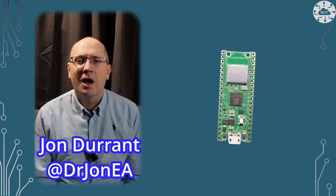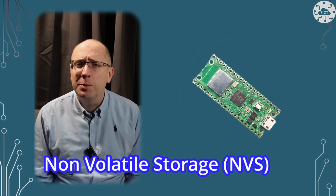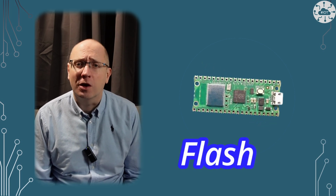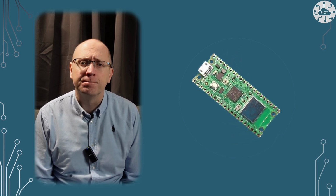Hi, I've been taking another look at non-volatile storage options for the Raspberry Pi Pico. The Pico comes with its own flash on board, and we can use it for more than just the purposes of storing code. It isn't trivial though, and in this video I walk through some of the steps and considerations. I look at options and examples to store your persistence variables into that flash memory.